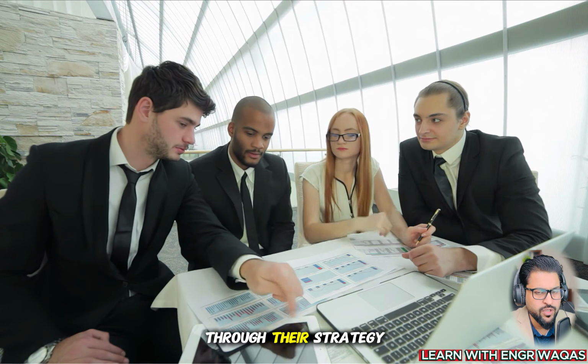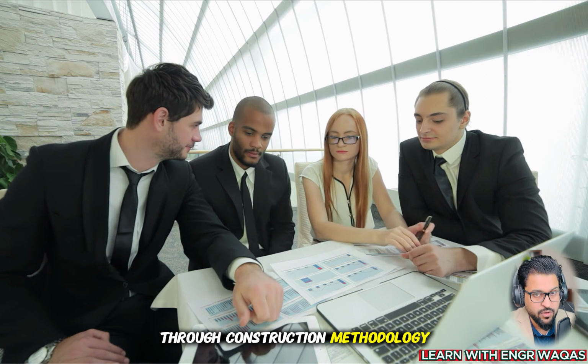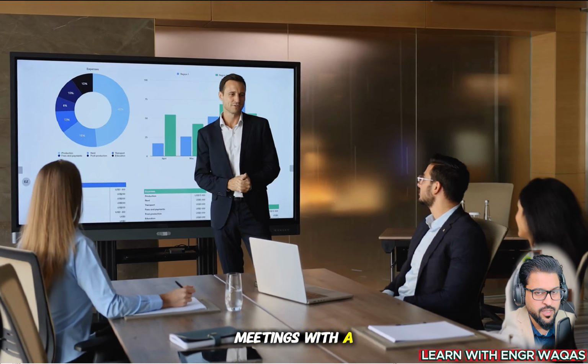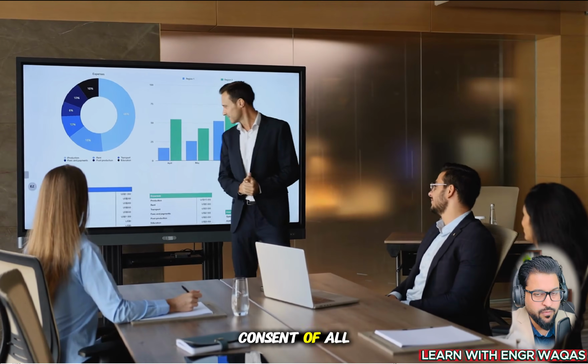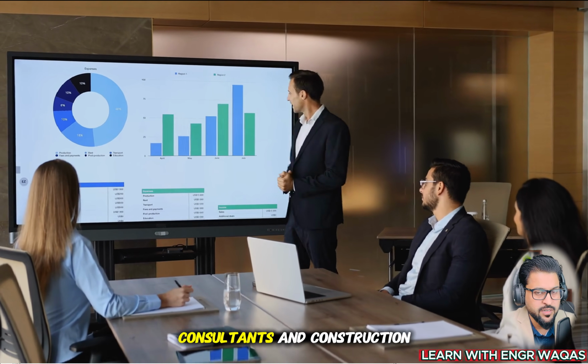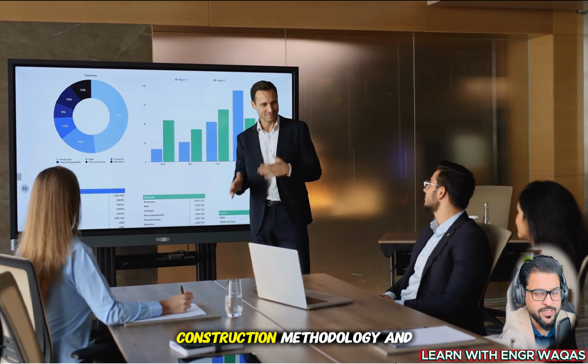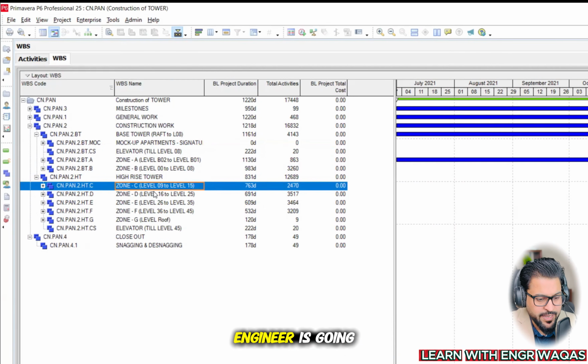So how are people going to decide? Through meetings, through their strategy, through construction methodology, right? All of these things go through meetings with the proper agreement and consent of all the stakeholders, designers, consultants, and construction managers. They are going to give all this construction methodology, and the planning engineer is going to take the WBS out of their methodology, out of how deliverables are defined within those meetings, right?